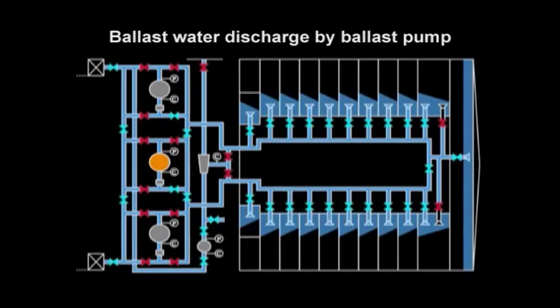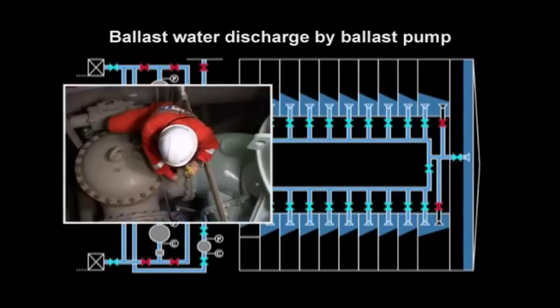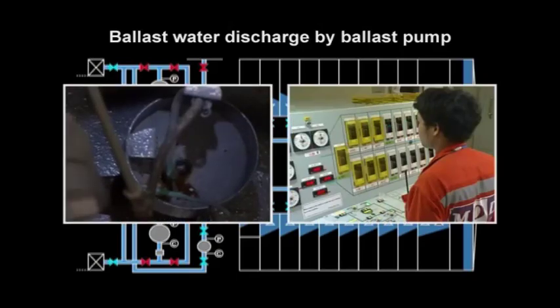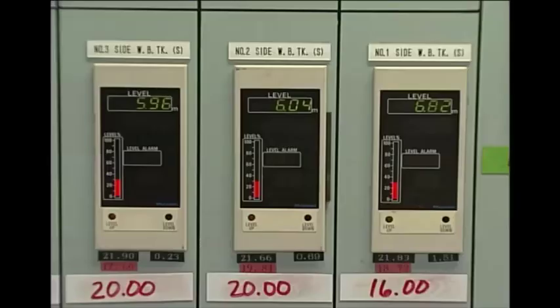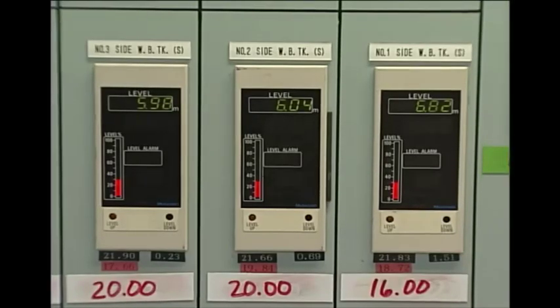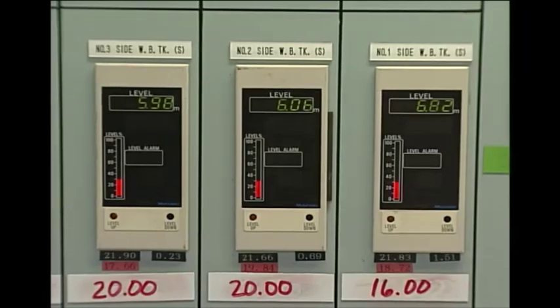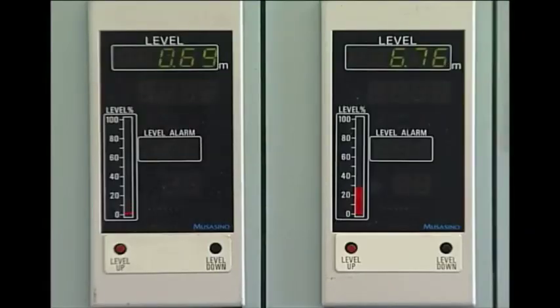The ballast pump starting procedures are the same as for filling. Make sure to conduct air purging from the pump and confirm the state of valves and gauges. Watch water level, since cavitation occurs as the level drops, which causes the waterhead pressure from the pump suction valves to decline. As the water level drops further to approach the tank bottom, now exercise precautions against air drawing. Watch the gauge carefully and readily respond to the risk of air drawing.